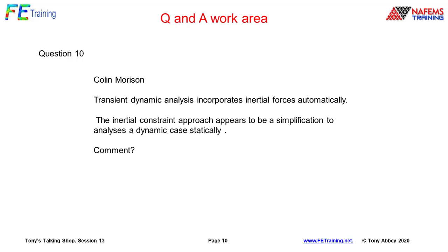Colin makes the point, transient dynamic analysis incorporates inertial forces automatically. The inertial constraint approach appears to be a simplification to analysis of a dynamic case statically. Can you comment on that? It's not. It is using Newton's second law. It's saying force equals mass times acceleration. So it's actually not doing a dynamic analysis. What it's saying is force equals mass times acceleration for the out of balance forces.